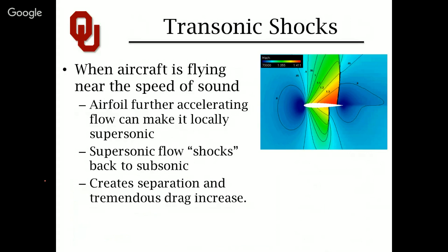If you reference the CFD depiction in the top right, which is important because this is very much a compressible flow scenario. You're above Mach 0.3, which is the Mach number at which we assume that flow can now be compressed just by the presence of a body passing through it. So you can see the flow actually slows down tremendously right in front of the leading edge. So V infinity is roughly Mach 0.8 in this case. It actually slows down to about Mach 0.7 if you look at the color scale.